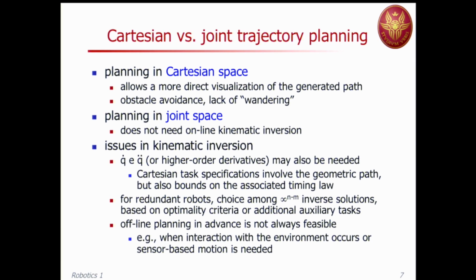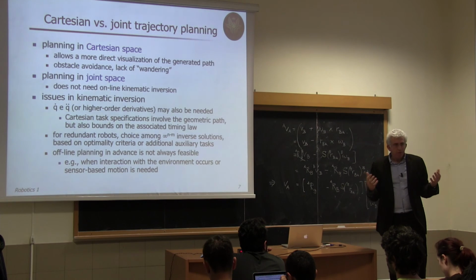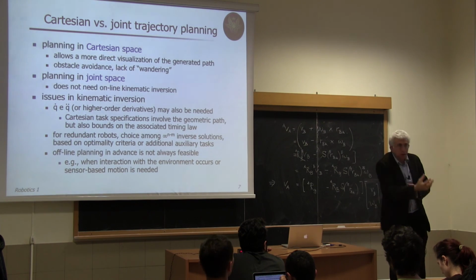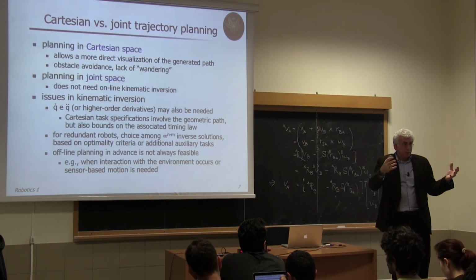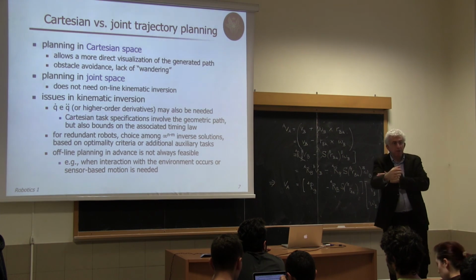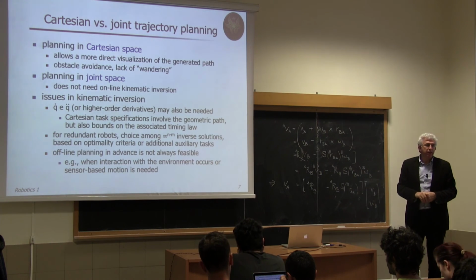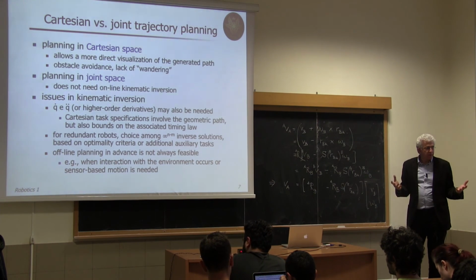For easy cases, when the workspace of the robot is not crowded with obstacles, then avoiding it with the end effector and trying to keep the arm close to the base will avoid collision. But if the robot has to enter into some car body, so the end effector may be free of collision, but then you hit with some part of the arm against the rest of the car body, so you have still a problem. So Cartesian is not enough in general.